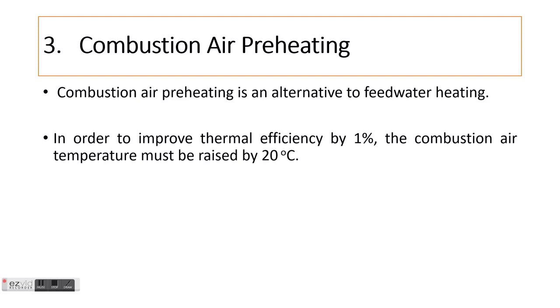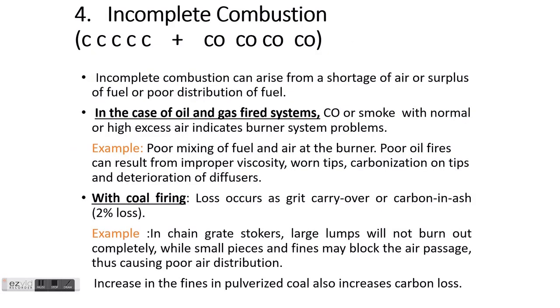Modern burners can withstand much higher combustion air preheat, so it is possible to consider such units as heat exchangers in the exit flue as an alternative to an economizer, when either space or high feed water return temperature make it viable. 4. Incomplete combustion. Incomplete combustion can arise from a shortage of air or surplus of fuel or poor distribution of fuel. It is usually obvious from the color of smoke, and must be corrected immediately.